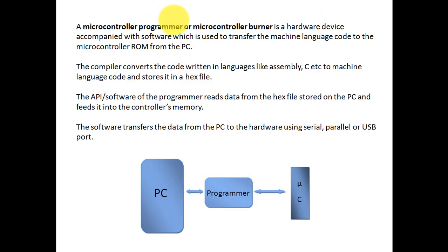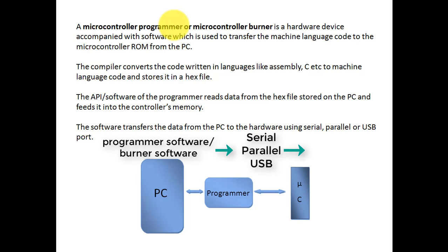A microcontroller programmer or burner is a hardware device accompanied with software, which is used to transfer the machine language code into the microcontroller ROM memory. The software of such a programmer reads data from the hex file stored on the PC and feeds it to the microcontroller's memory. Such software transfers data from the PC to the hardware using a serial, parallel or USB port.